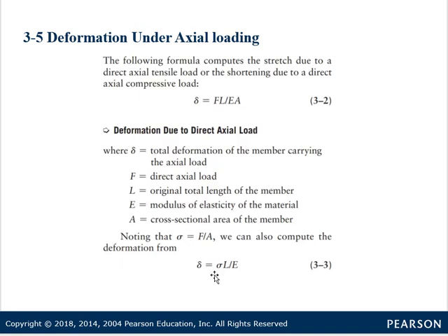Also notice that we can rearrange this equation a little bit because we know that stress equals force divided by area. If we substitute that relationship in here, our deformation is related to stress times the length divided by the modulus of elasticity. Okay, so that's how we calculate deformation under axial loading.